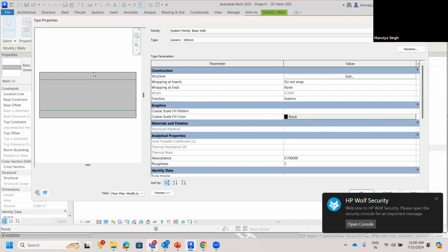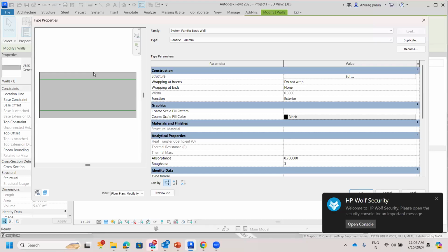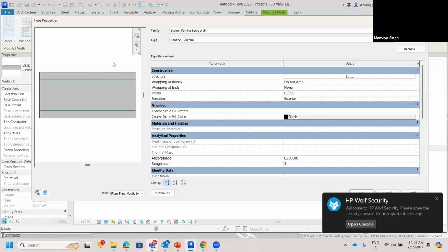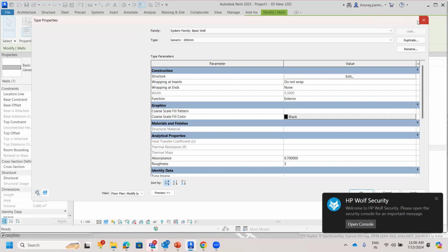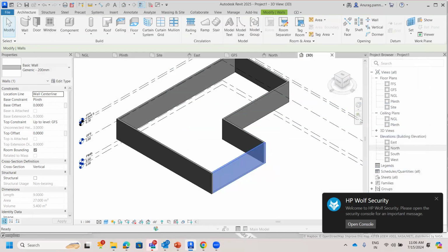And excuse me, if we have to add some glass panels on the walls, how can we do that? Glass onto walls directly becomes part of a family. It doesn't have any directly incorporated option, though it has certain options with curtain walls. If I move on to architecture, I have certain options of working with curtain grids and walls. In that case, if you need an opening with a completely fixed glass, you have to move on to family types. You have to generate that family, load that family into the project, and then you can work upon it.